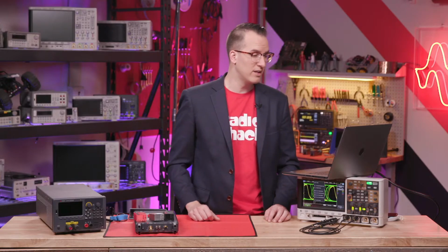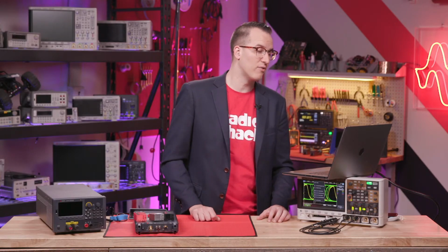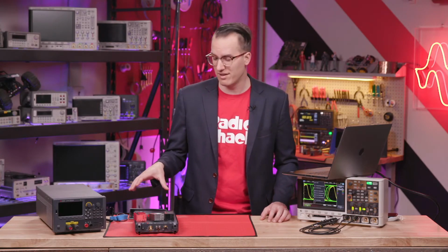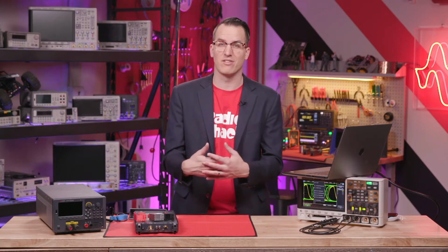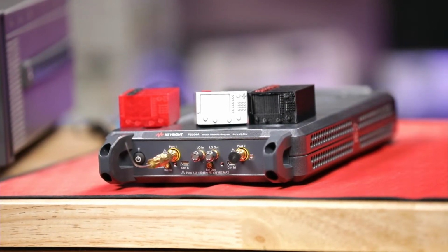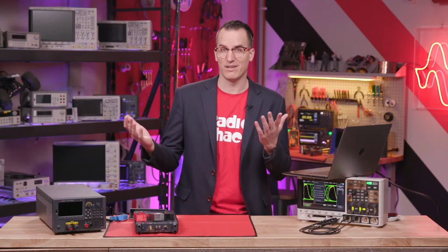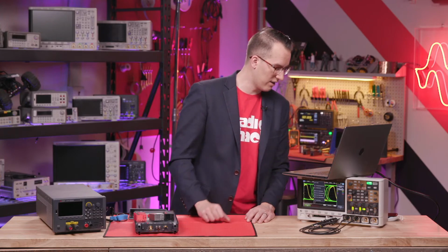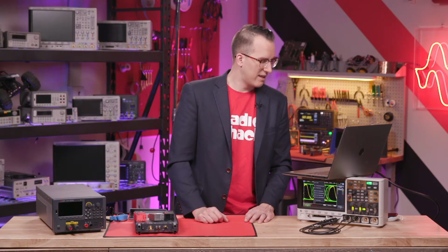Is it possible to tune individual stages of radio receivers with the VNA? Yeah, doing impedance tuning and device tuning, a VNA is great for that, especially those interconnects. The trick is being able to actually get to the measurement points and doing the different stages, but I don't see any reason why you wouldn't be able to do that with a VNA.